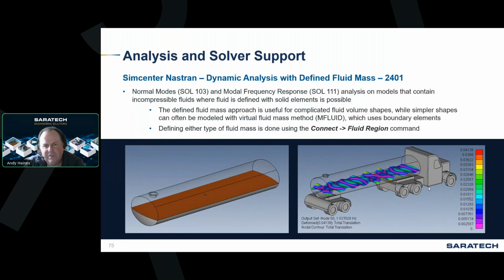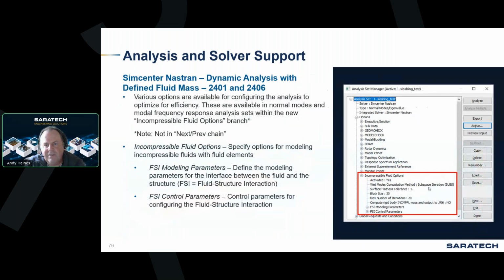Back to those incompressible fluid surfaces. Essentially, what you could do in something like this is just see the sloshing modes, and all of those are created via that. And then there are quite a few options you can specify in here for a modal analysis or frequency response analysis, including a number of FSI modeling parameters and control parameters, FSI meaning fluid structure interaction.